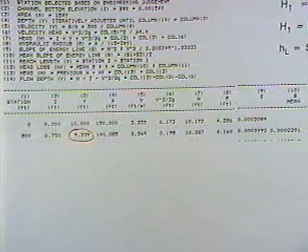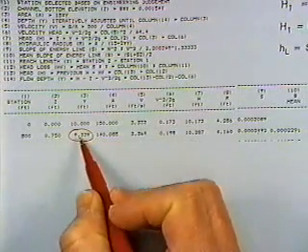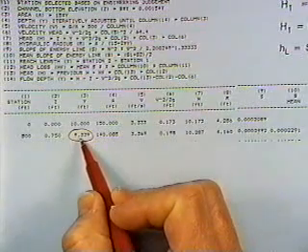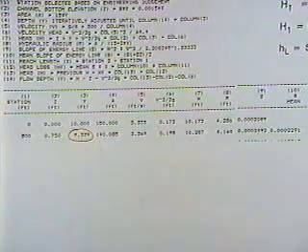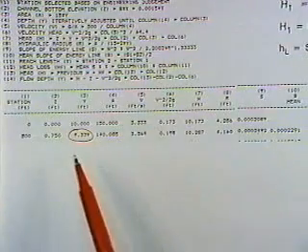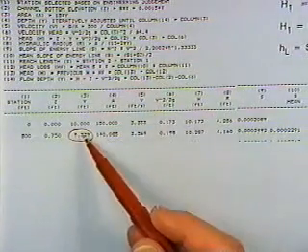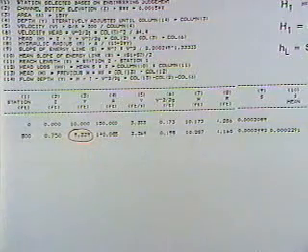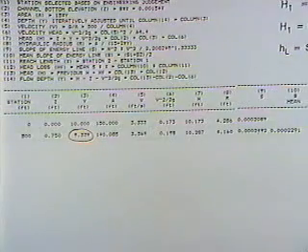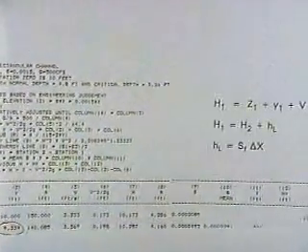So the first time through, this might come out to be 9.5. So then you've got to take the 9.5, plug it back in, and do the computations over again. You've got to keep doing them over and over again until you're assuming a depth, and then all the computations come out so that if you back the depth out, you get the same depth. Another way of saying the same thing, everything's got to hold simultaneously. This expression's got to be valid.